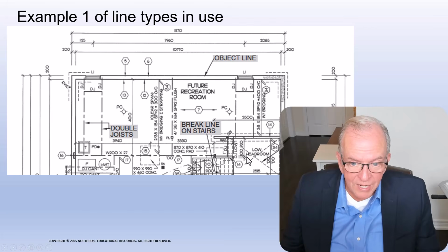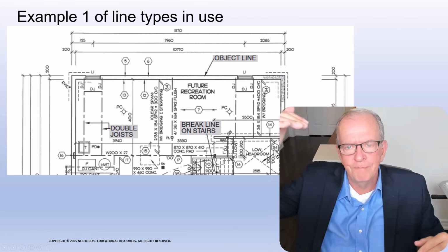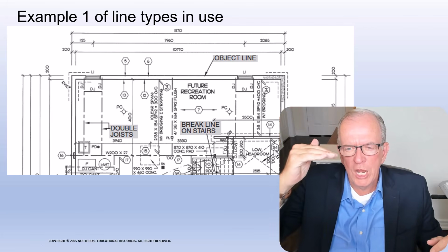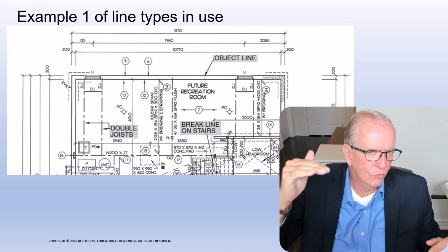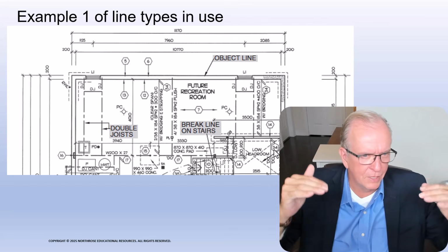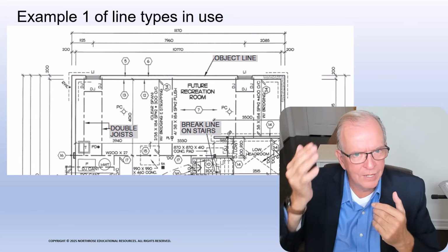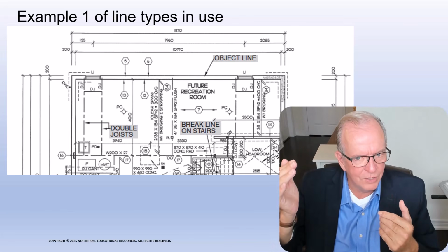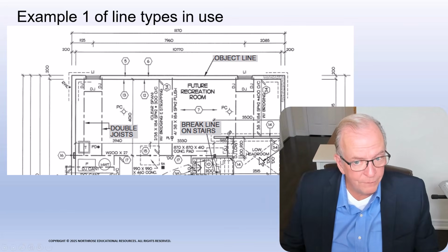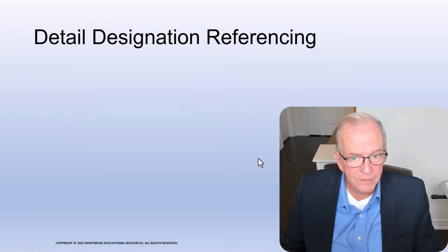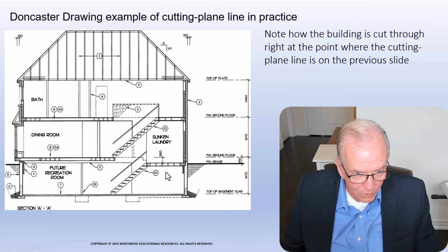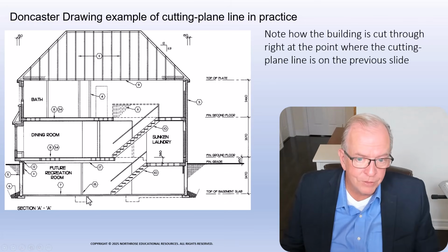The dash line as an X, that's this designer's way. They like to show an X when they're saying that there's a change in ceiling height or floor height. So something's a little bit different. It's kind of flagging it for you. They're telling you before on the next floor plan, sunken laundry area. On this floor plan, well, if it's sunken, it's low headroom. You don't have the same kind of headroom here, right? So you don't get like an 8-foot ceiling here.